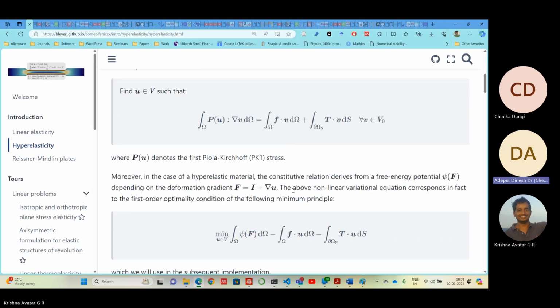I think this is actually important to discuss. We are not looking at it from a practical point of view. Say you are designing something, and since you are taking the engineering stress and you assume engineering stress throughout the material life, then the actual stress is different, no? We might get the body into failure sooner than what we thought because we are not considering real stress. Do you understand what I'm trying to say? That's true.